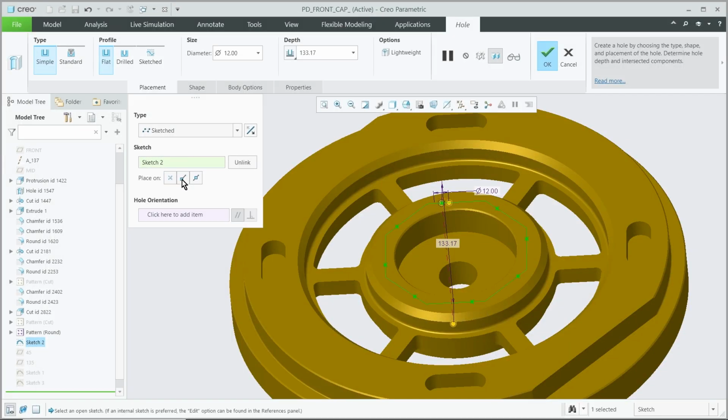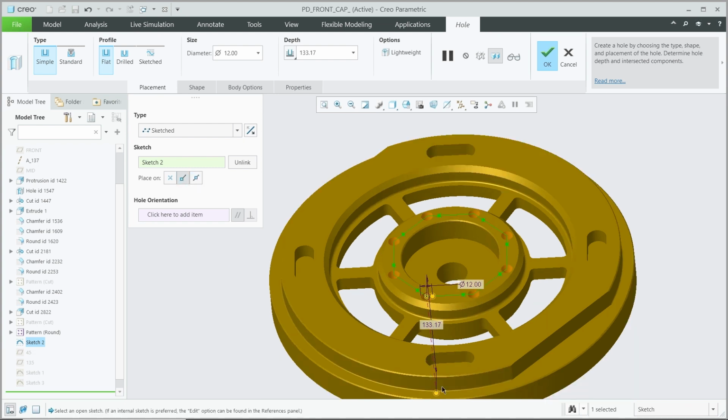I could say put the holes at the vertex of our octagon. So we've got our 8 holes here, or I could say at the midpoint. So any straight line at the midpoint of that line, and we can see those there. And I can mix and match them, right? So I can have it at the midpoint and at the vertex. But this allows us to go in and actually kind of create a pattern.